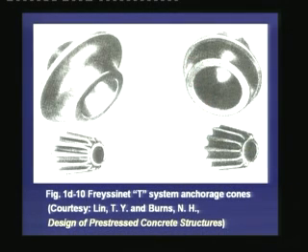This is a simple Freyssinet T-system anchorage cone. Here you can see that these wedges will sit inside these blocks during the tensioning operation of the strands. Now, this wedge is for an individual strand of the prestressing tendon.